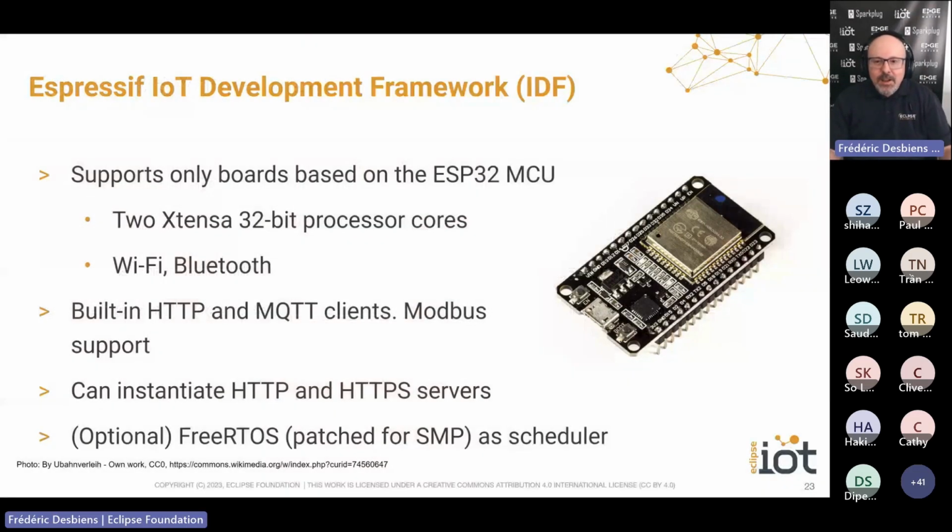Another interesting option is the Espressif IoT Development Framework, or IDF. This is a software stack that really targets their very popular ESP32 microcontroller. And it's a very good one, right? With dual cores and Wi-Fi, Bluetooth, and all of that. IDF itself comes with built-in support for MQTT and HTTP client, Modbus support. It can even provide you HTTP and HTTPS servers.